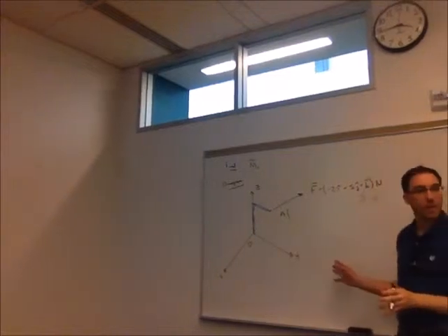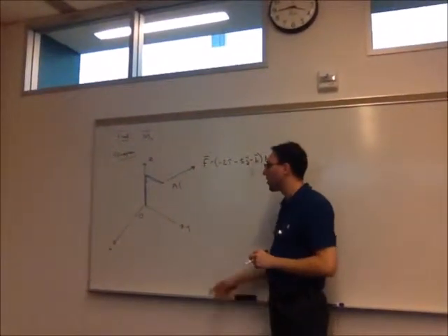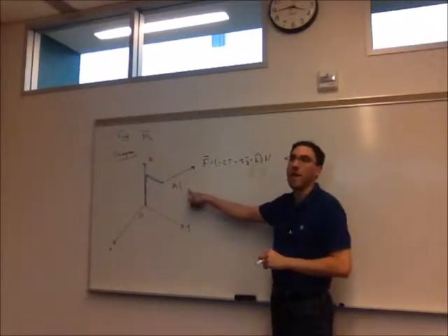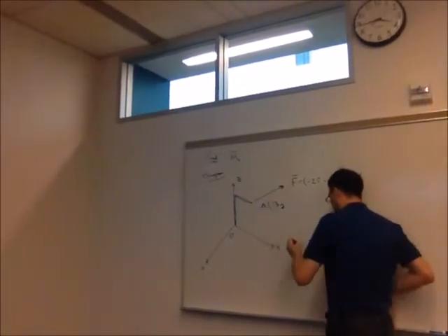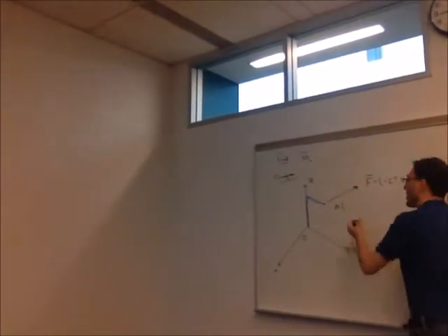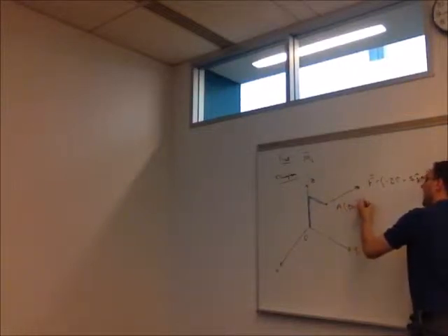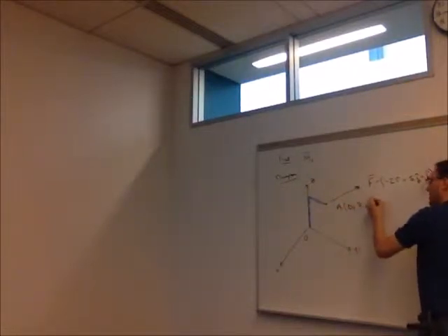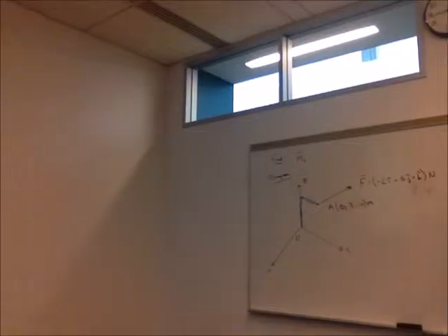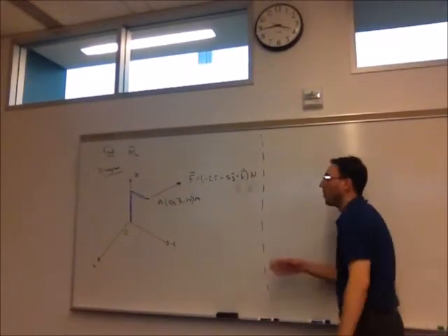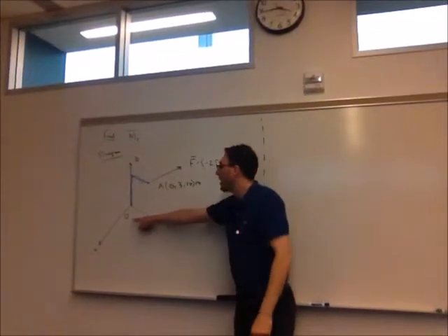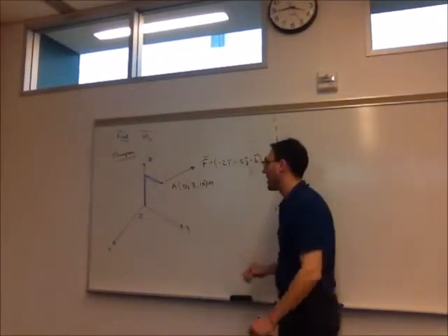And because we're in 3 dimensions, I'm going to just go right away and put the coordinate down of A. So for A, we have to go 3 in the y direction, so 3J, in coordinate form, 0, 3, 10 meters. So one force at A, O is the origin here, so that's where we're going to start.